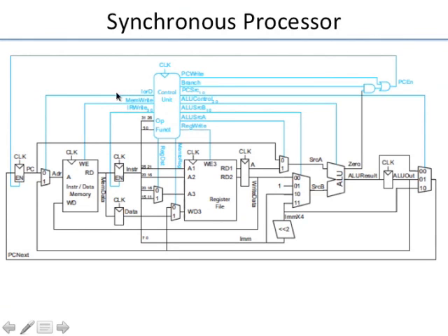And if you notice here, the computation itself can happen over multiple cycles. It's not that it needs to finish in one cycle. It can happen over multiple cycles, and that is again sequenced using this clock signal. CLK is a clock signal. It is a global signal. That means the whole chip, everywhere, gets the same clock signal. It's required that the clock appears at almost the same time throughout the chip.